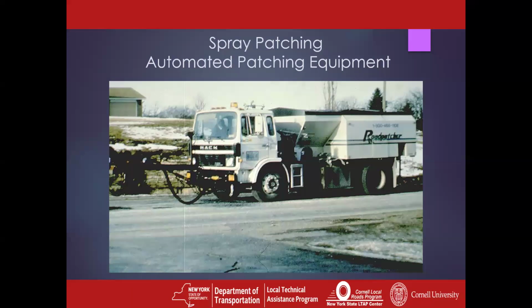You're bringing it up to your hole. You're blowing it out quick. You're going to be spraying in a coat of tack. You're going to be spraying in aggregate, and then you're going to be spraying in more liquid, and then you're driving off. It is self-leveling, self-consolidating, does a real nice job. And the folks that we've talked to that have used this technology like it. So it is available in New York, not used a whole lot, but seeing growing use.